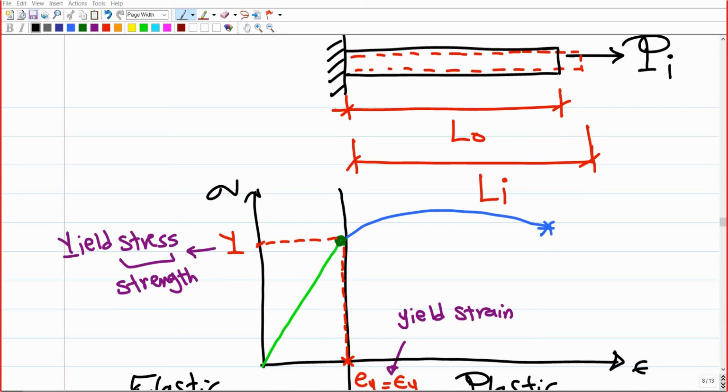So again, the objective is just to expose the material to a very high force to produce very high stresses that should be higher than the yield strength of the material. This is why we agreed to give Y to the yield strength or the yield stress of the material, and we have to expose the material to a stress level higher than the yield strength to bring the material to plastic deformation. Once we move to the plastic deformation, the material will exhibit a permanent change in shape, and this will give us the final product according to the concept of the manufacturing process.